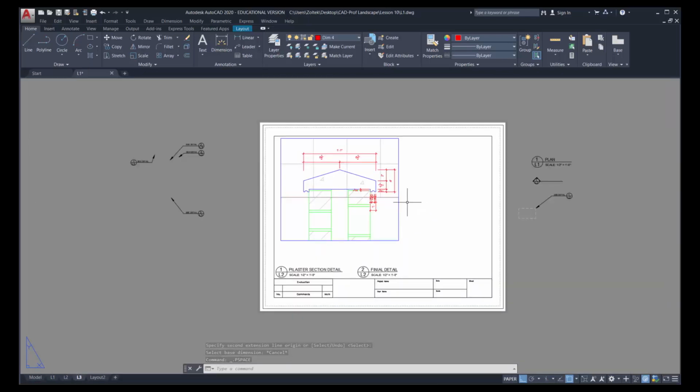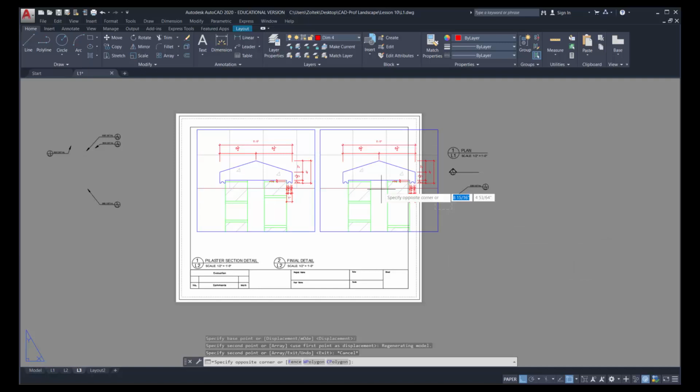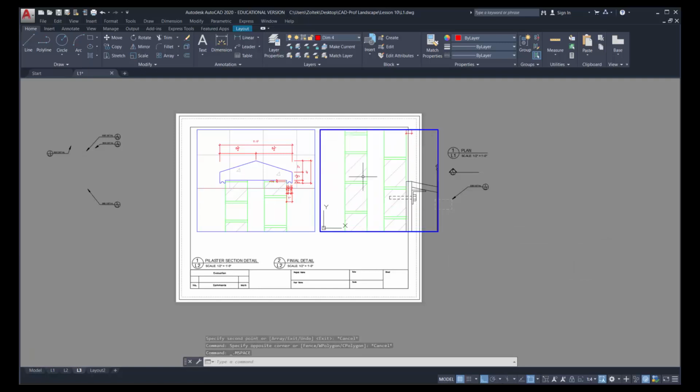Now we've got the other two details, which are the upper and the lower bracket. I can take this viewport and manipulate it, or create another viewport. It doesn't matter. I'm going to copy this viewport over, and I'll find the bracket. So I double clicked inside, press and hold the wheel. It's the same scale, so I'm not manipulating anything in terms of scale.